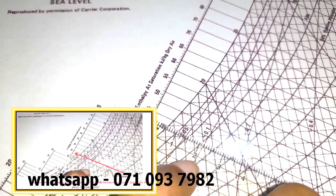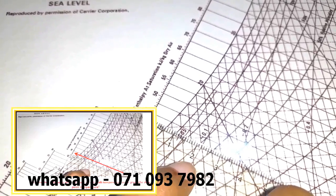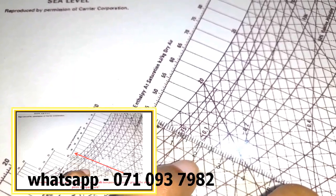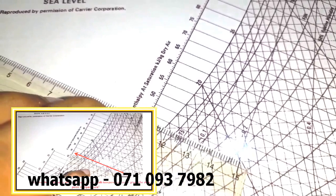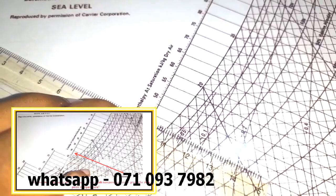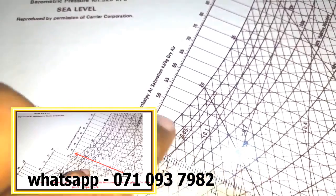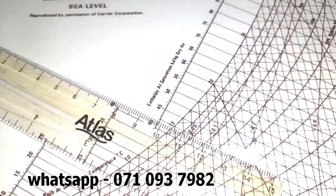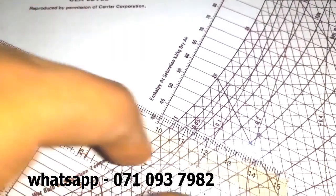Now just come parallelly up to here. You got it? Now you can very clearly see this line. When I reach parallelly from this 15 degrees Celsius wet bulb temperature line to here, it will direct to somewhere here. Now see this line is in between 15 and 16. This is the parallel line that I obtain when I come parallel with respect to the 15 degrees Celsius line. It will stop here. It is so clear that it is a value in between 15 and 16, somewhat similar to a line right in the middle. So let's call it 15.5.